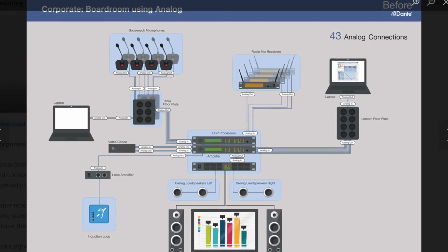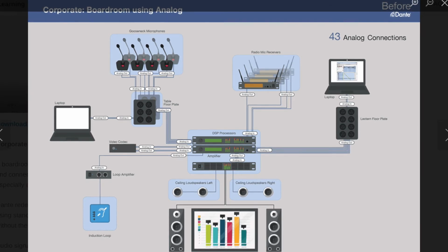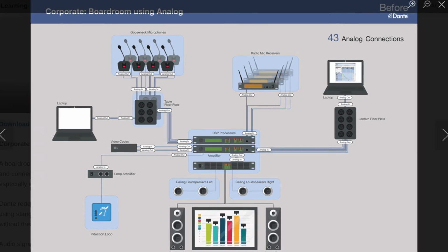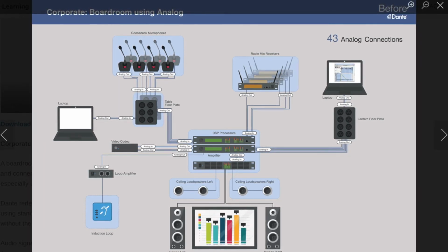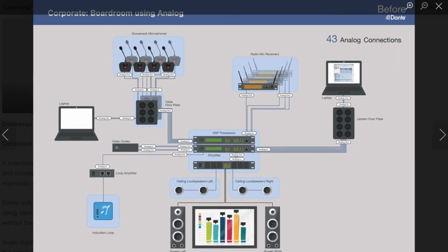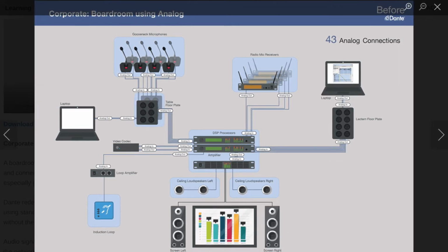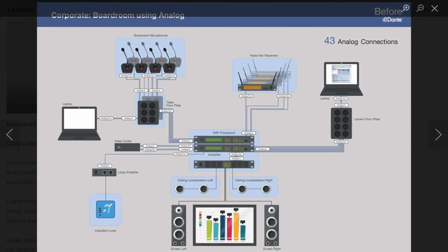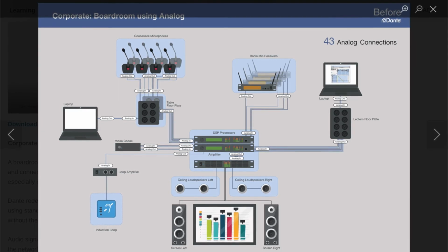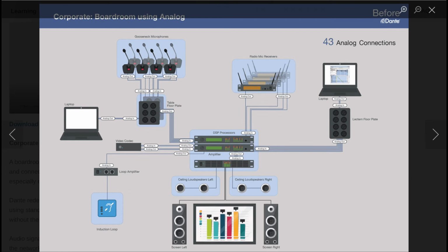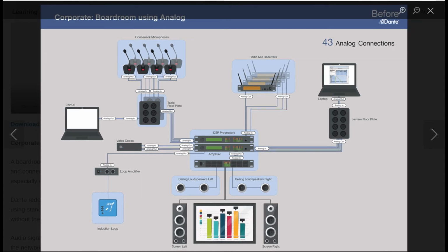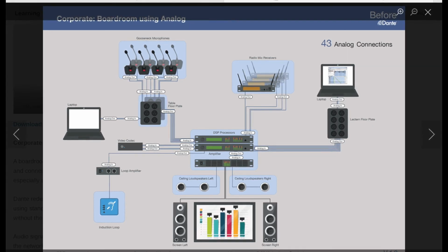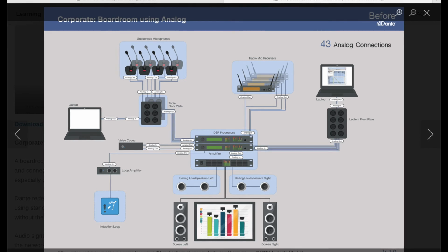This means that audio devices using the same network can be sent wirelessly through any sound device, no matter where they are located. So because of this, the Dante sound system provides a standard audio over internet protocol, IP for short, network. And this can allow digital audio to be packaged by an IP packet. Now, these packets can contain clocking information and IP addresses for sources and destinations to be written in them in order for them to be sent digitally to the correct destination via network.